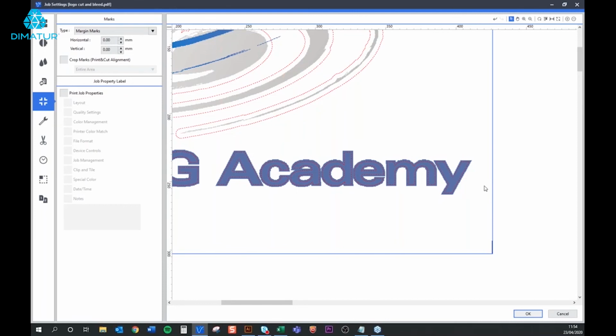You can also add a border to your margin marks. You could specify a border in the horizontal and vertical axes. So you could allow, for example, a 20 millimeter white border around your design before the marks are applied. Or you could just add a couple of millimeters so that you've got a little bit of space to line up and chop off the actual marks. Hopefully that made sense about the marks. So that was just a quick look at the difference between trim marks and margin marks, and we'll jump on and see if there are any questions.